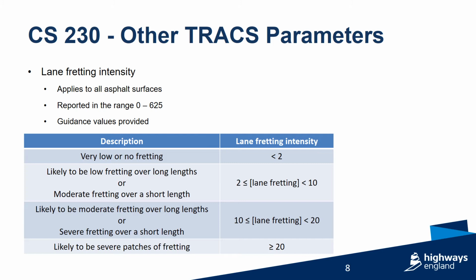Similarly, in the 10 to 20 range, two scenarios exist, either moderate fretting over long lengths or severe fretting over short lengths. There is likely to be very severe patches of fretting present when the lane fretting intensity is reported as 20 or more.